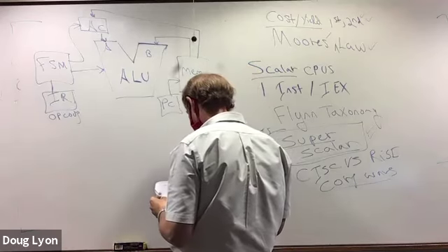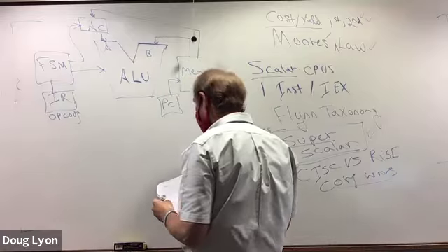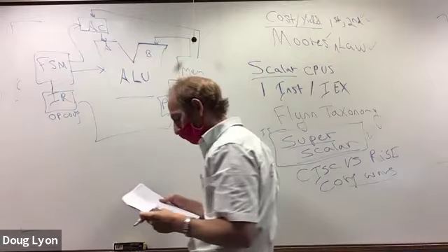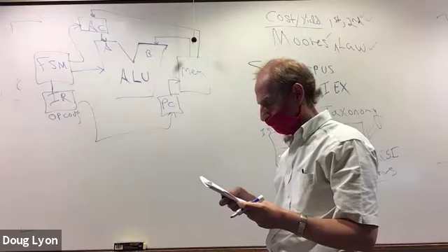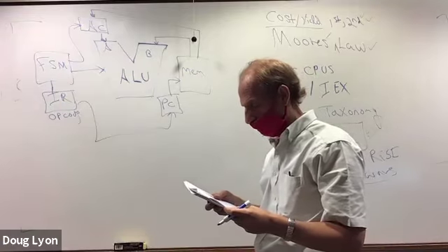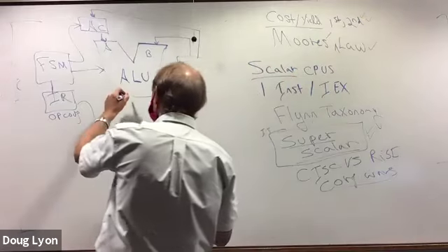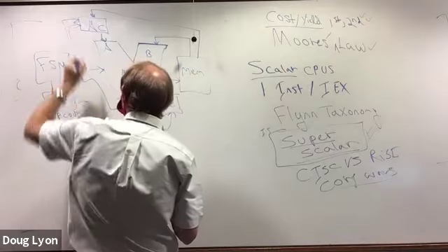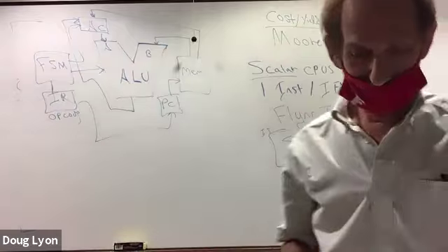That gives us an address. And what we'll do is we'll use our instruction register to modify the program counter so we can have jumps or we can have simple increments. And that's about all I want to do, other than find a way to take the output of the ALU and perhaps run it into our accumulator. So we'll just run that into the accumulator as well if we want to store something. So that's sort of my block diagram.